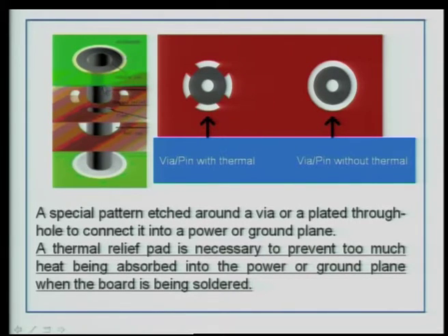Now, the hole passes through the second layer, and here you can see the thermal relief is provided. So, this is copper, no copper, copper, no copper. And if you can imagine the hole going through the third layer, here there is no copper at all touching the plated through hole, the copper is here. So, this is an anti-pad structure, and it ends up in the fourth layer.